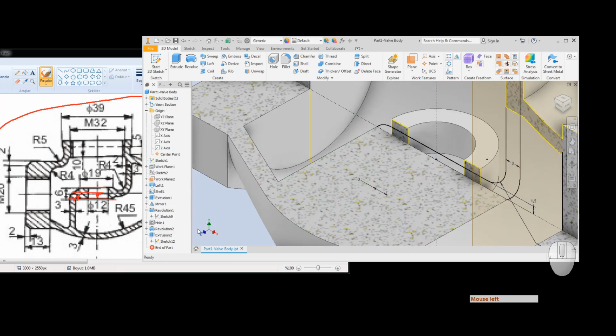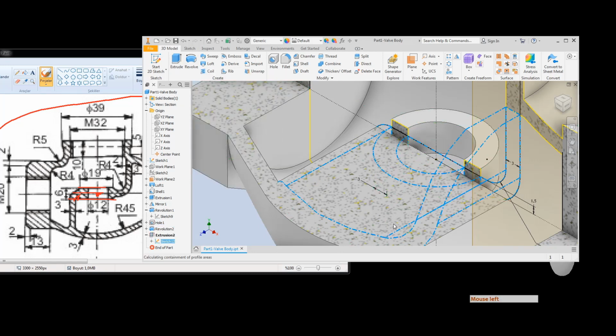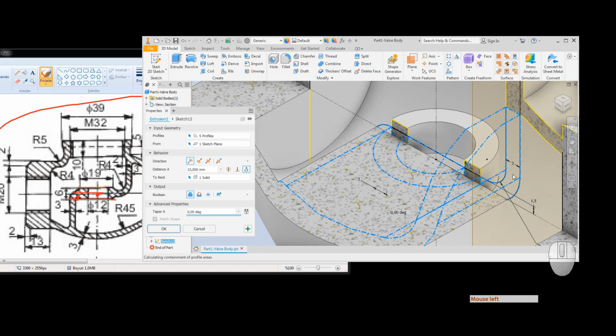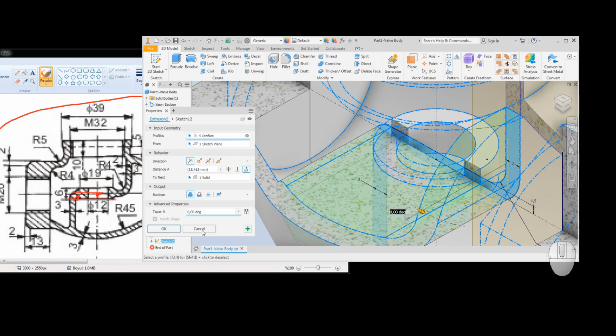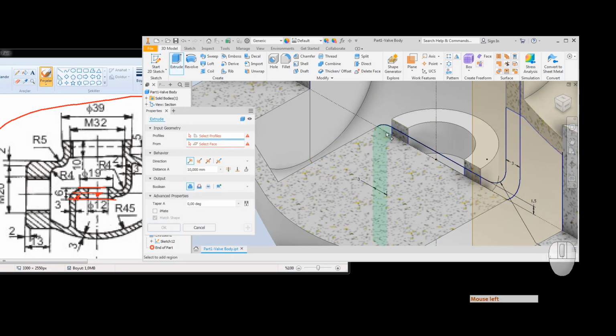Also, we will combine the inside. I'm sorry. Yes. Also this side. Also this side. We will remove the inside again, the extrusion cut, revolve cut process. Yes. We just create the wall to prevent the passing flow. To use the extrusion, sketch again, because I do not want to draw that sketch again and again. For extrusion, again, I just need the upper profiles.